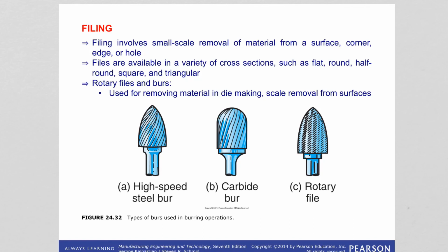In the process of filing, the metal removing action is the same as in sawing, in that chips are removed by cutting teeth that are arranged in succession along the same plane on the surface of a tool called a file. The difference is the chips are very small here, and therefore the cutting action is slow but easily controlled, and the cutting teeth are much wider.